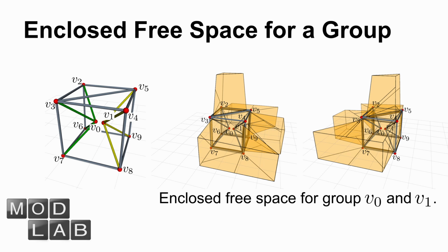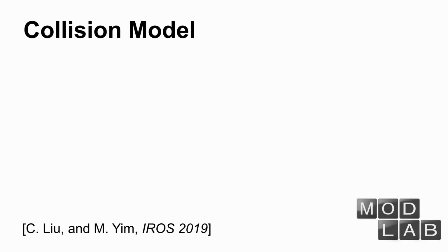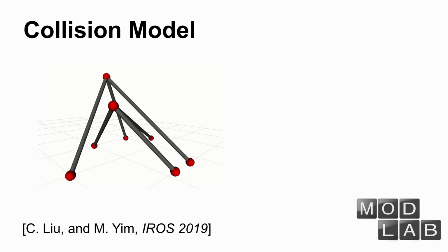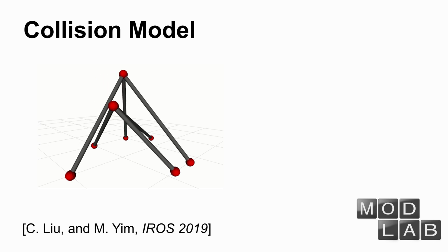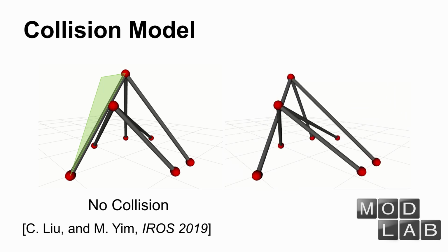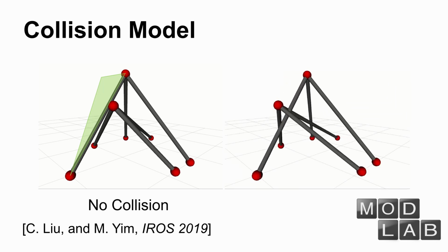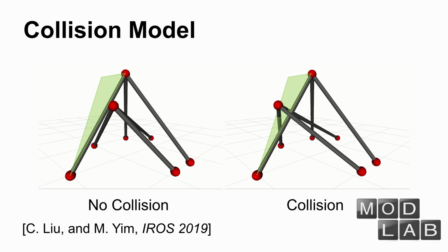The singularity avoidance condition can also be modeled as a plane that can be added to the obstacle region. The sampling space is significantly decreased and collision check greatly simplified so that the RRT framework can be applied efficiently. An efficient collision model can be applied. We just need to check the intersection between any still member with the triangle generated from the moving member, or compute the local obstacle region for a group of nodes and check the collision.